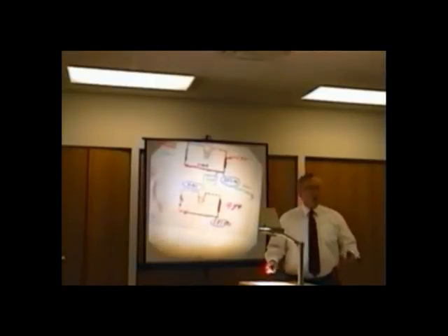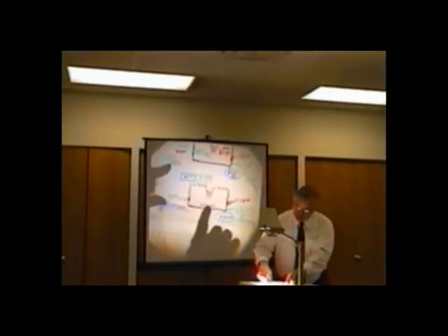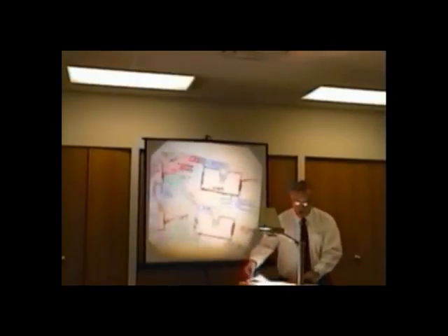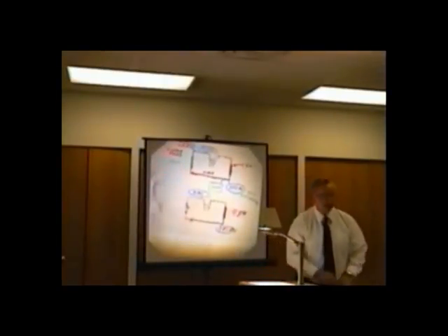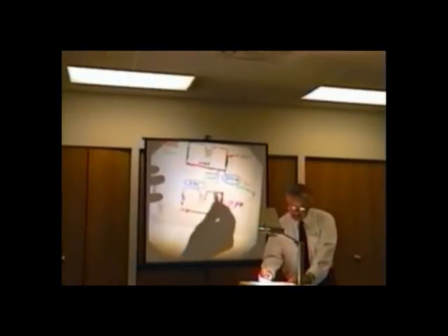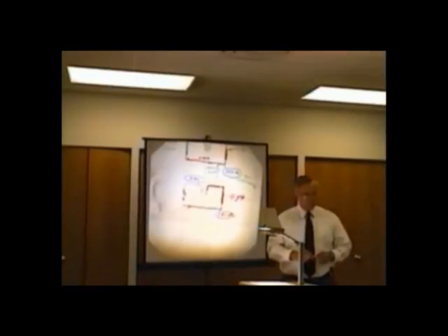So the technician says, oh, I have a low low side and a low high side, I must be undercharged, because didn't an undercharge give you a low high side and a low low side? He says, I don't have enough gas. I'll make it cooler. Let's add gas. Now the pressure goes up. See what I mean?